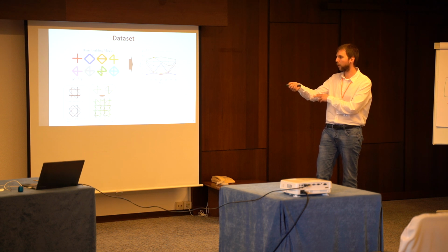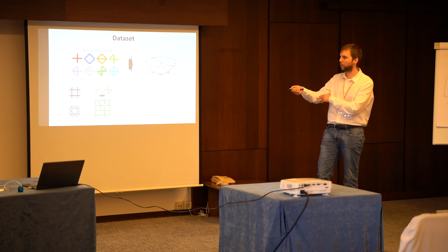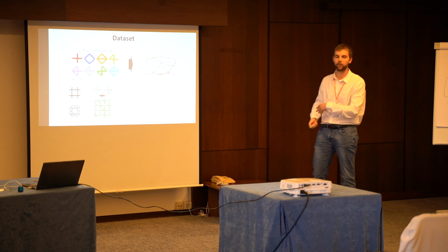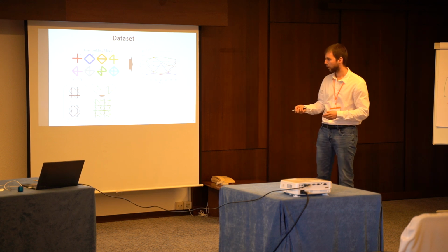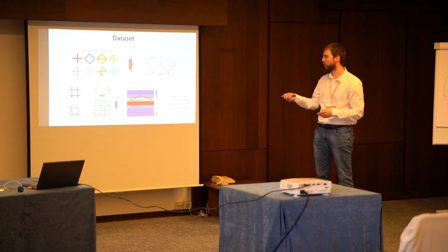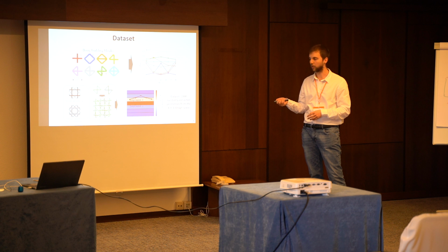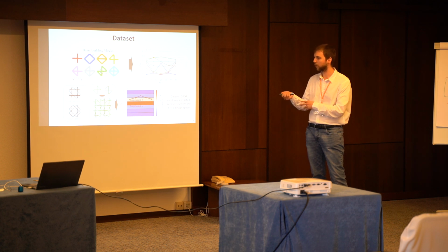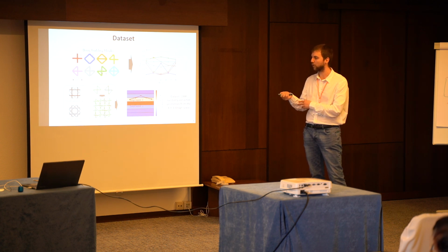We benchmark our results with a recent result on sponge-inspired designs, where a recent paper shows that this design is one of the best in terms of buckling strength. We randomly extract 2,000 geometries from the whole 4x4 unit cell design space, and we show here that about 40% of the geometries inside the dataset outperform the sponge. Let's call it sponge A for simplicity, which is this one.